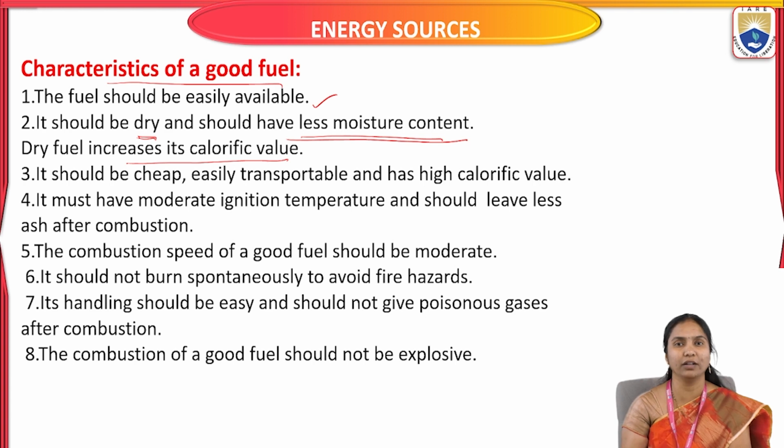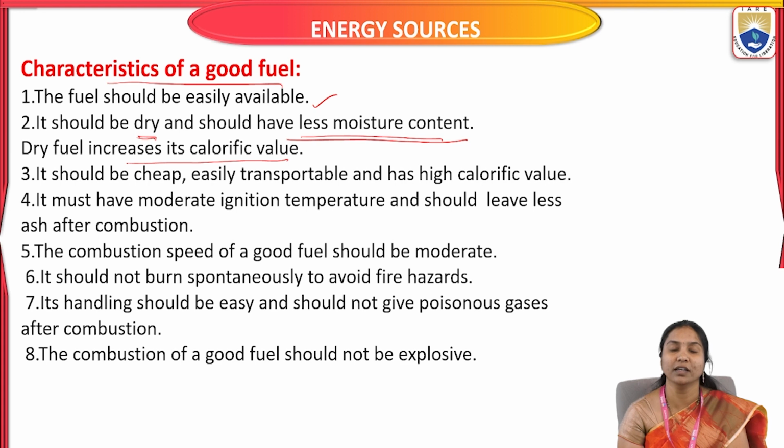So what is the meaning of calorific value? It is how much heat is liberated when 1 kg, or one unit mass, of fuel is burning. That value is known as calorific value. A good fuel always produces a high calorific value. If moisture content is present in the fuel, it reduces the calorific value.